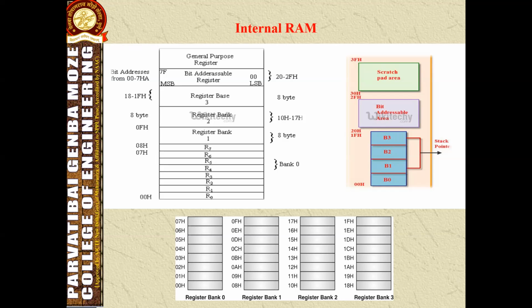This avoids overwriting the data. At the end of the routine, all the register contents are popped. This pushing and popping is extra work the processor has to do, and the time required for it is called the latency period.